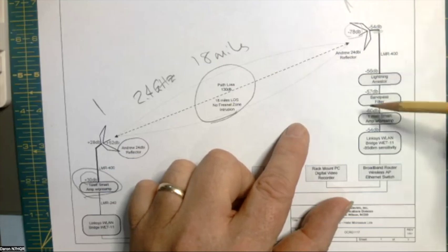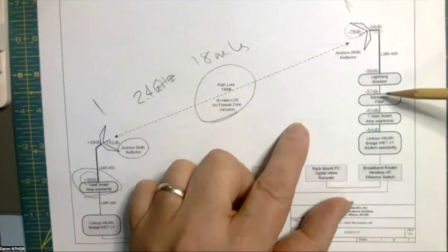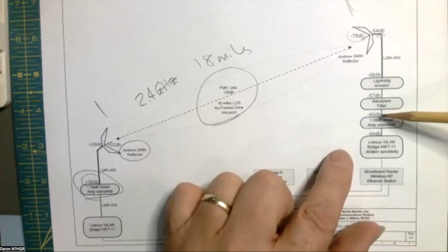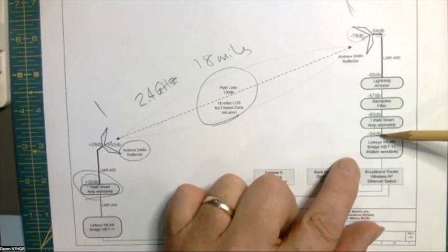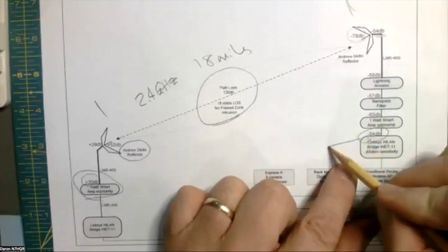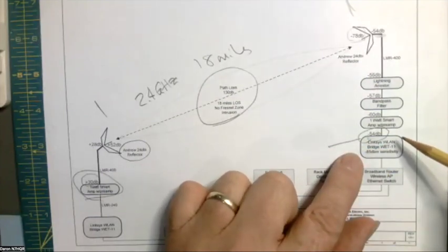And then because there's other equipment up there on the hill, we have a bandpass filter, so we only hear our radio. But that costs us 3 dB, it looks like. So now we're down to negative 60. We get a little boost from a preamplifier that's in the amplifier at this end, so we're back up to negative 54 dB. So that's our signal going into the radio up there on the hill.